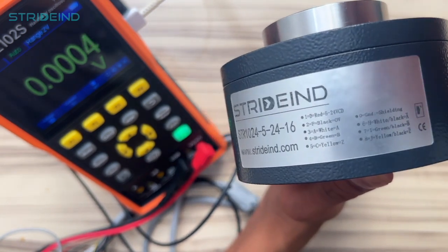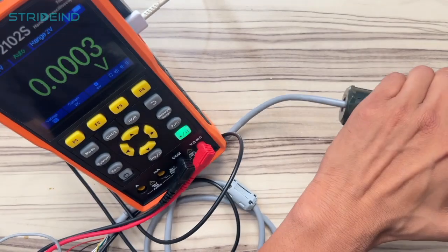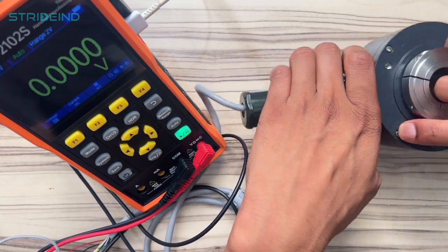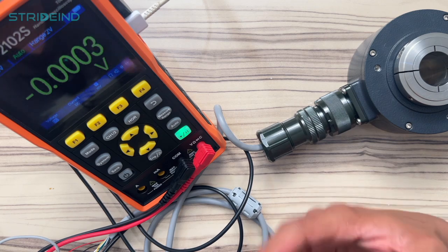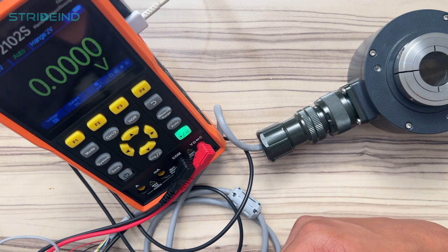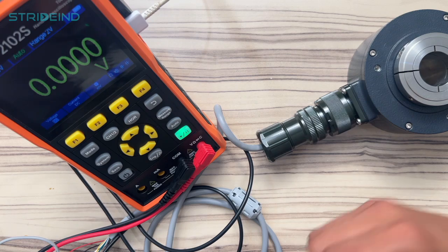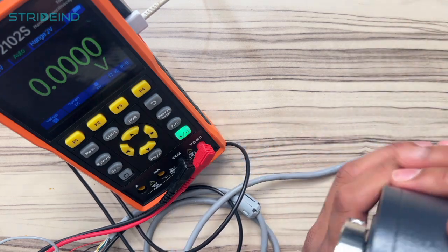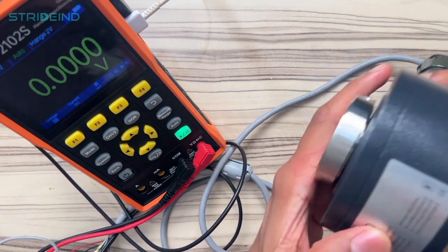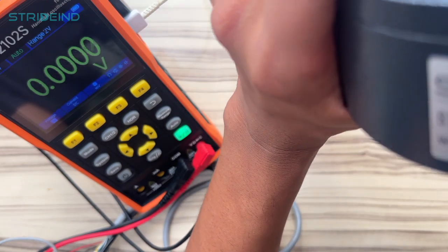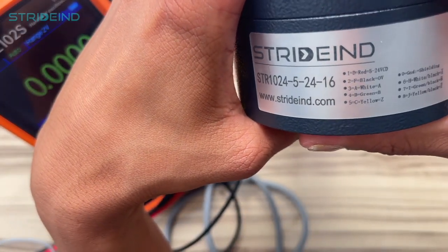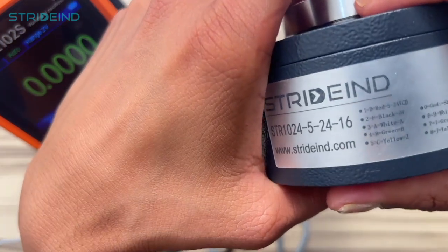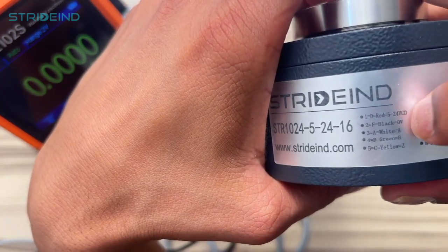First we will learn how to connect them, then we'll look at how to troubleshoot with a multimeter and with an oscilloscope. First of all, your connections. In connection you have input. Input is your 24 volt and 0 volt in.